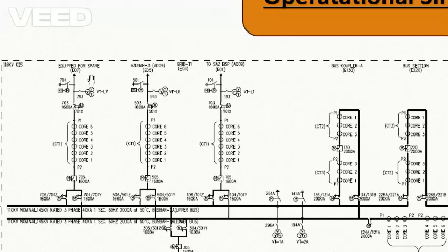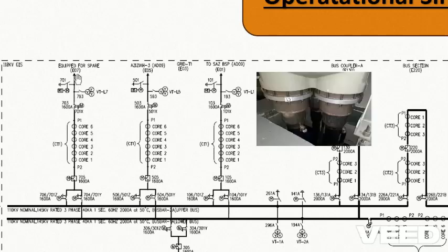okay guys, so now the power starts from here by the cables. Normally in GIS we are inserting XLPE cables of size 630 mm square to 2000 mm square. These are high voltage underground power cables, and they feed the power at this point.